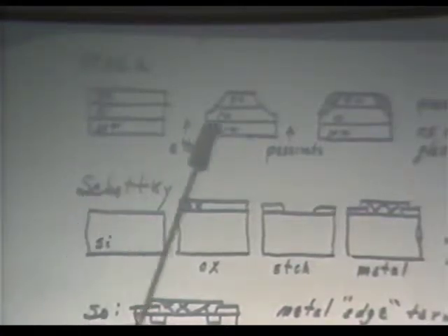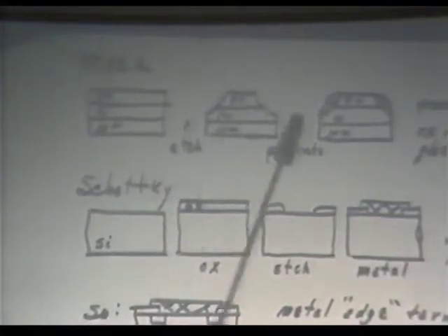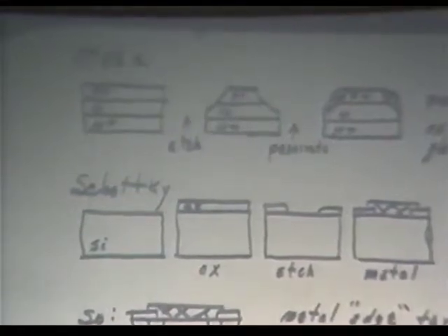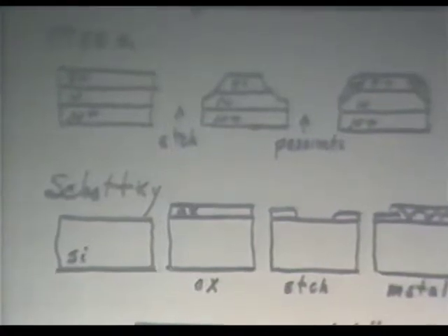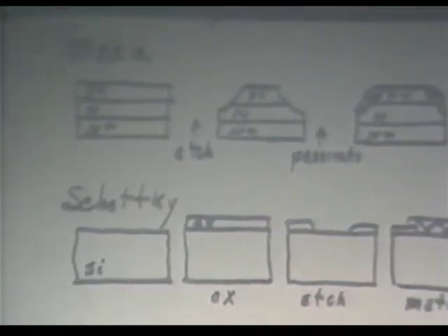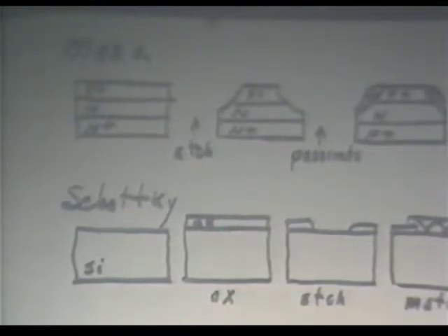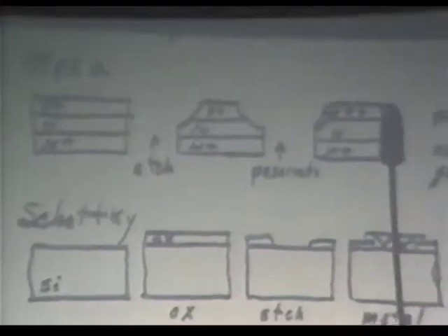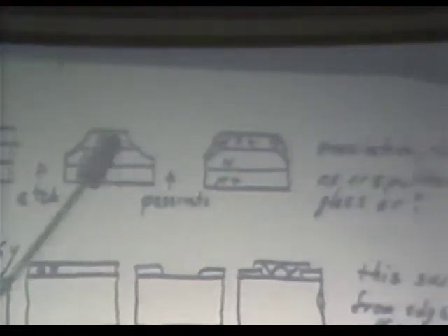It's a double diffused structure that's been etched, and this incidentally would be done in the wafer form, not in the chip form. But we've got a slice full of these, and we etch these areas away on all the parts. Now we still have a slice full of these little truncated volcanoes, and we use some process, sputtered glass, thermal oxide, whatever, and coat the junction that would have been exposed to the world if we had just left it in this form.